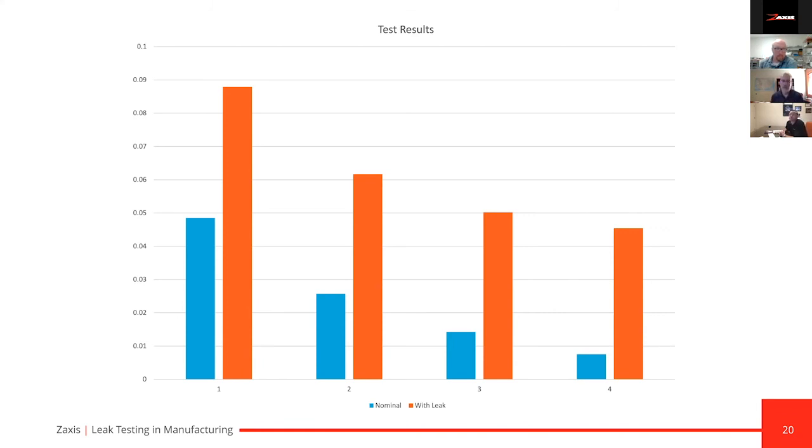Yes, I pulled up this chart again because Doug talked about this one earlier. When Charlie says the 4-to-1, typically you're going to want to adjust your fill and settle time so that when you get to the test, your decay, your non-leaking part is at least a fourth of what your leaking part is if you're looking at those graphs.